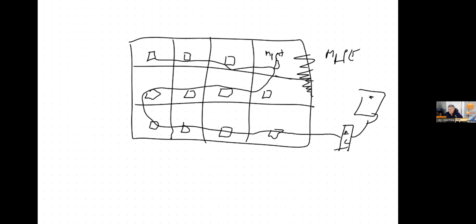I've got an illustration in the book somewhere from the site at Blue Rock Station that shows shading on one little panel reduced the output of that panel by 90%. So if they were all hooked together, shading on one panel might cut your entire array's energy production by 90%. But if you isolate it to a single panel, that panel is affected, but none of the other ones are.